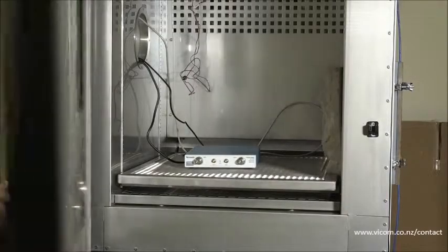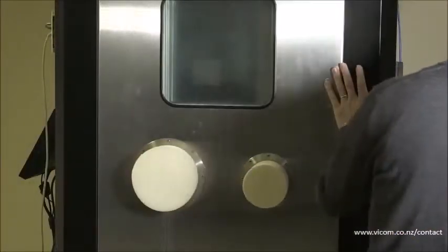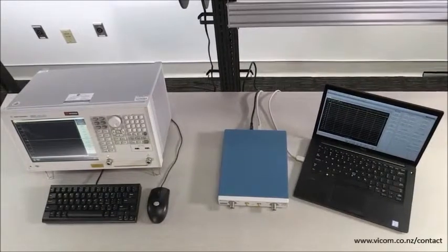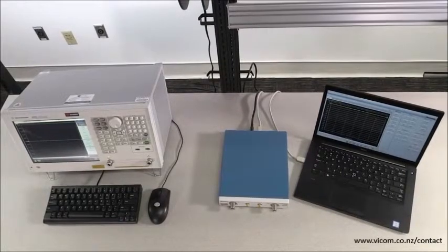Measurement drift. This is how much the measurement changes over time due to changes in the test system caused by heat, vibration, or instabilities. This is also a figure of merit for how well the instrument maintains its user calibration over time. And lastly, form factor, such as size, weight, and power.